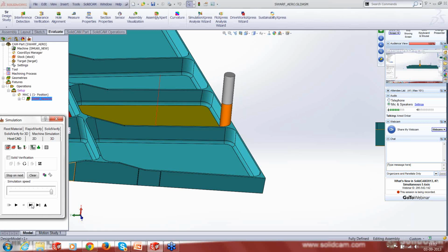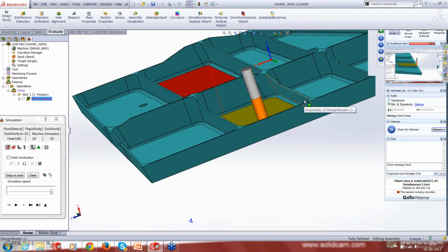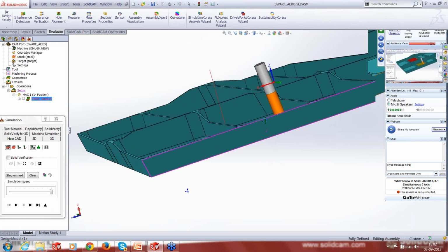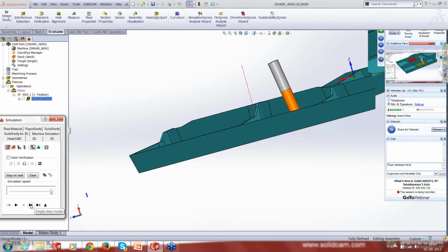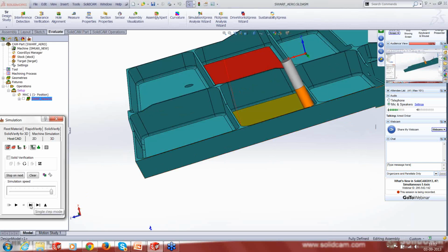Now it's going to have a straight approach. It's going to be almost straight on both sides, but now it's approaching another wall which has a negative draft. As it approaches, you can see that it is already changing its lag angle again. It's changing the lag in such a way that it doesn't need to do any kind of major transition at the fillet. At the fillet, it's only going to do a very minor transition, and it's back to the wall.